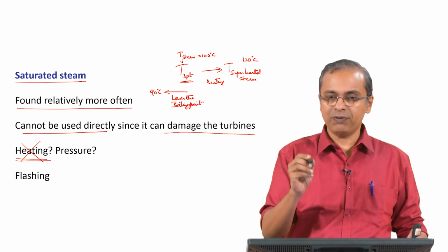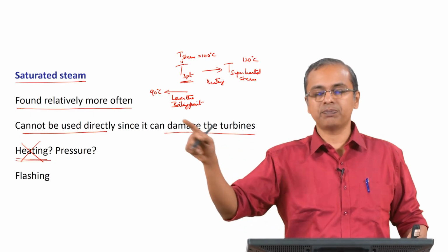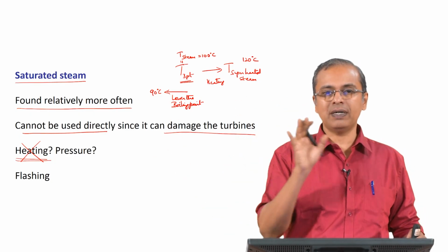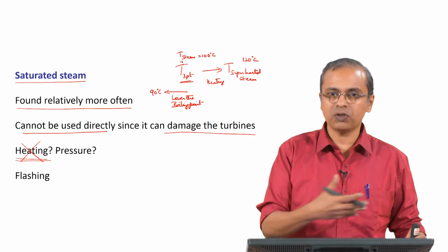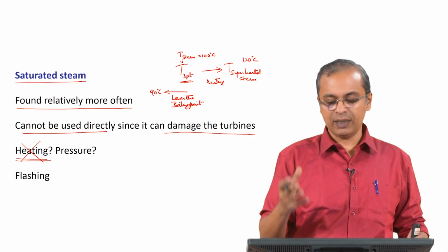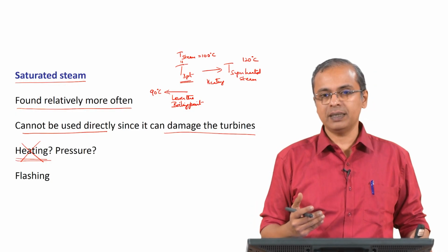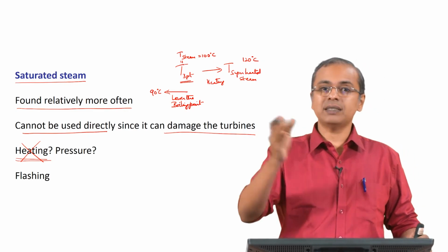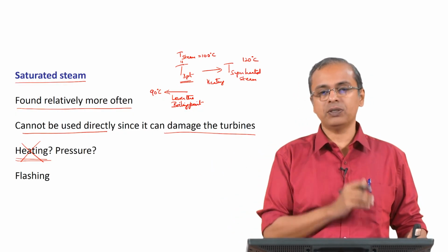If you think about it carefully and look up this information, it will always say the boiling point of something at a given pressure. The pressure part does not register to us because we only went looking for the boiling point, and the pressure is always assumed to be 1 atmosphere because most of the time our operation is at 1 atmosphere. So, the boiling point of water is 100 degrees C at 1 atmosphere. If you drop the pressure significantly, you can decrease the boiling point. If you increase the pressure, you can increase the boiling point. So, the boiling point is variable and depends on the pressure.